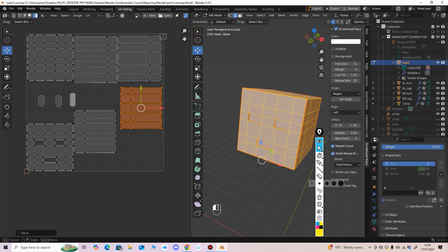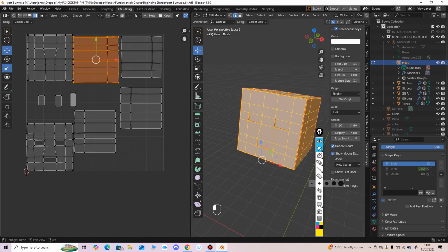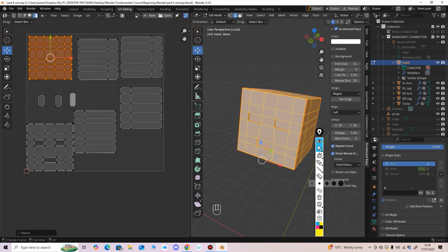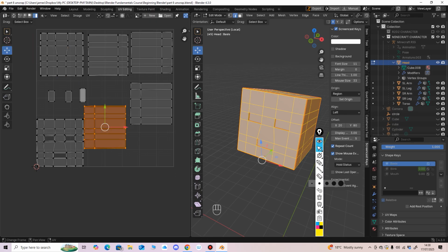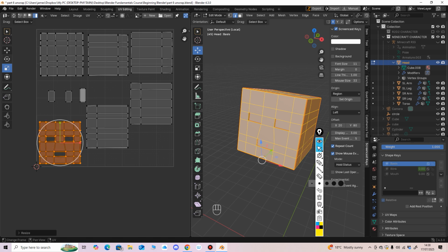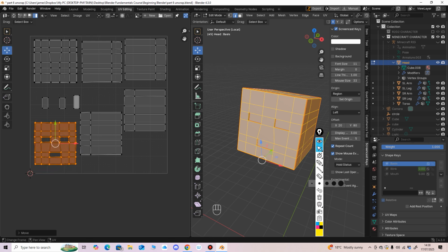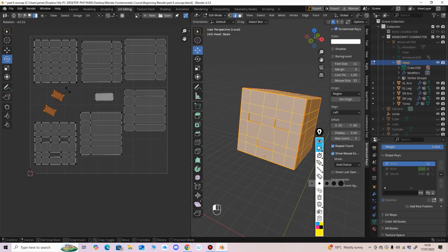So in your UV editor here, scale things down a touch, so you've got nothing overlapping. Because back in the day that used to crash your machine. And it may still do. You've got overlapping UVs, especially if you're applying normal maps, things like that. I'll just spread things out. You've got our faces there. That is the mouth. Move that over. That's your two eyes.